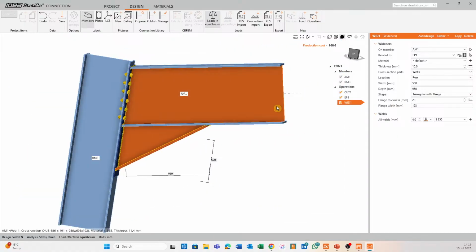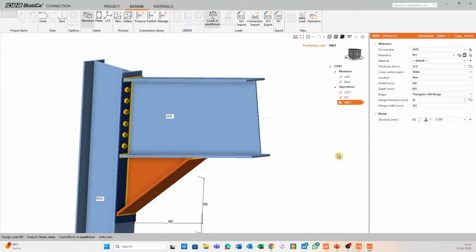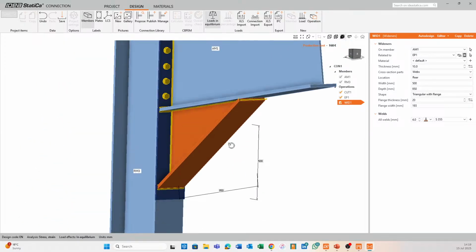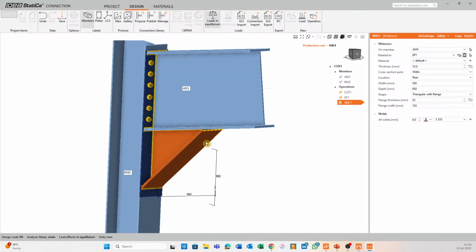There's a reason why that member all of a sudden extends, and that just has to do with how the stress distribution and those sort of things work for members of specific sizes. It is related to the actual height of this member, and that's definitely something to look into a bit more when it comes to working in the IDEA StatiCa space.